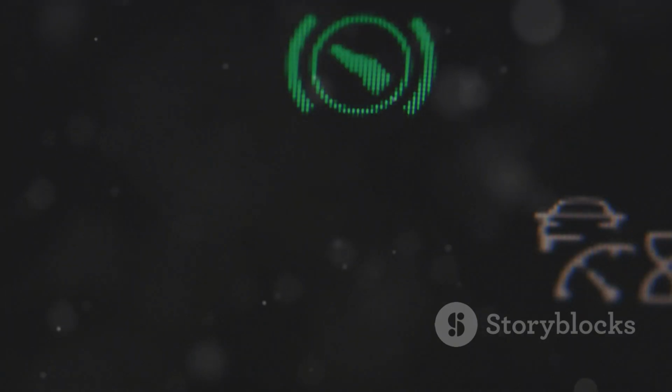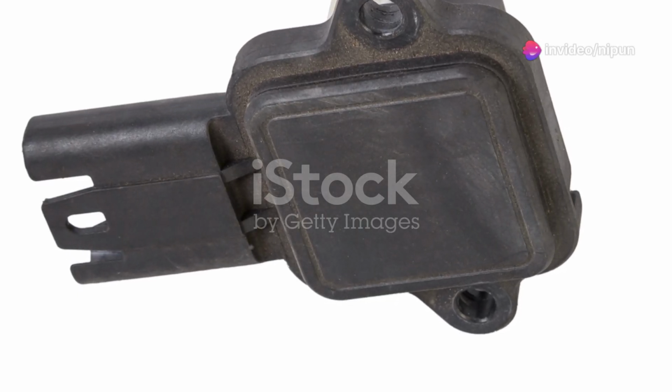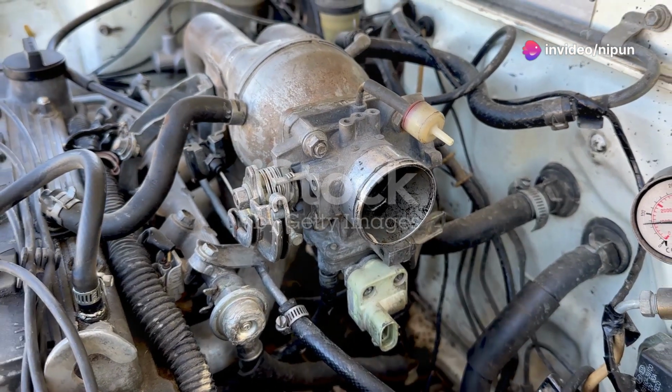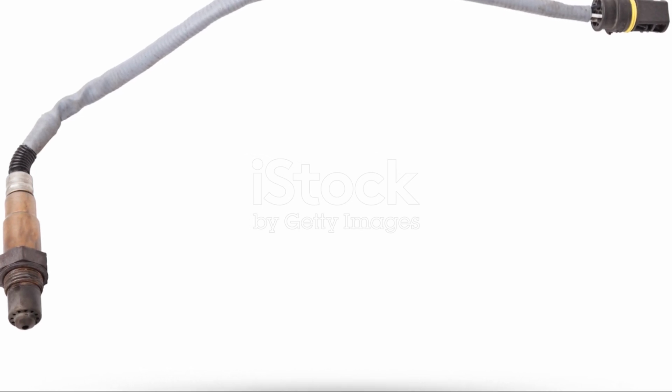Sensors play a vital role in providing the ECU with the necessary data. The mass airflow, or MAF, sensor measures the amount of air entering the engine. The throttle position sensor, or TPS, relays the position of the throttle valve. The oxygen, or O2, sensor monitors the oxygen content in the exhaust gases.